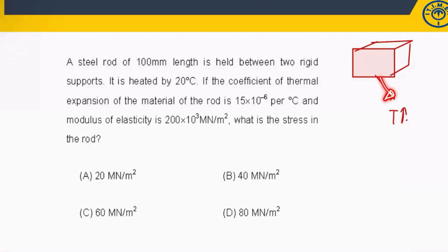Because of the temperature increase, this will try to expand, yes or no? But because of the fixed support, there will be some reaction. Something is resisting the expansion of this bar or cube, so in that case stress will develop.